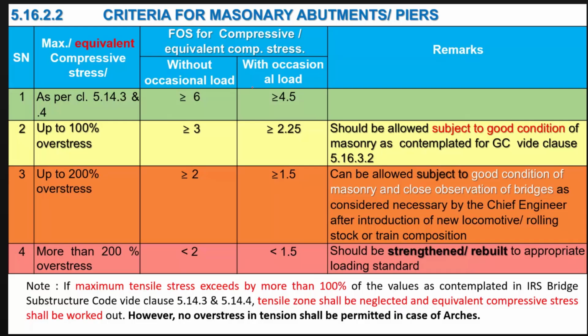If it is compression, then okay. If it is coming in tension, then the equivalent compression has to be calculated for that. Whatever the maximum compression is, if it is within the permissible limit as per clause number 6, then no problem. We can clear the bridge.